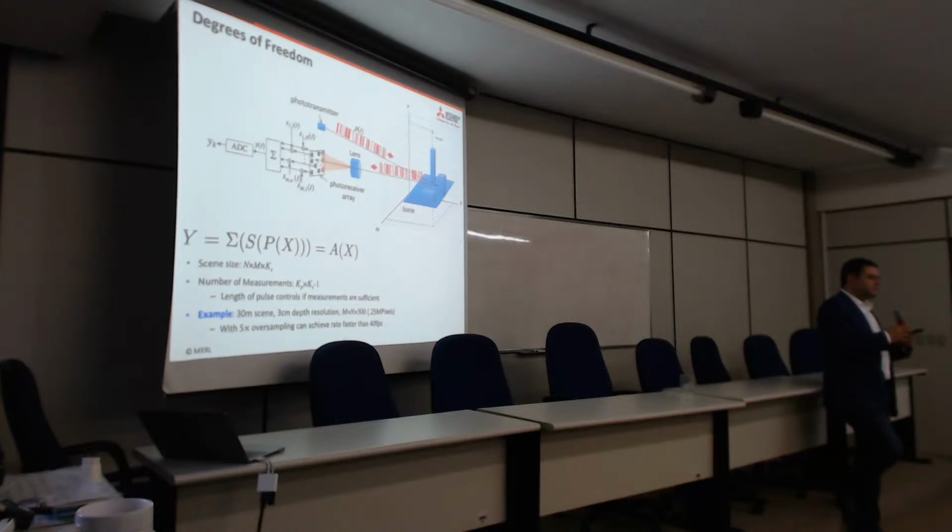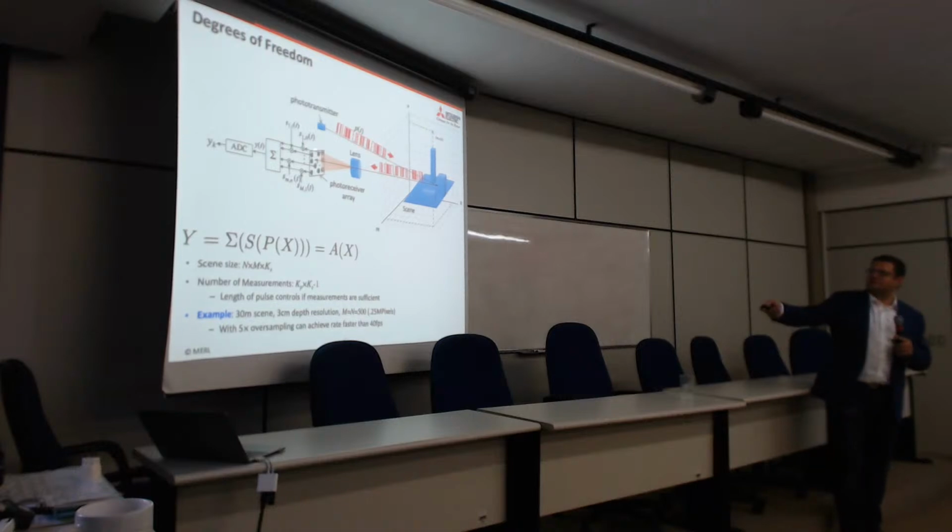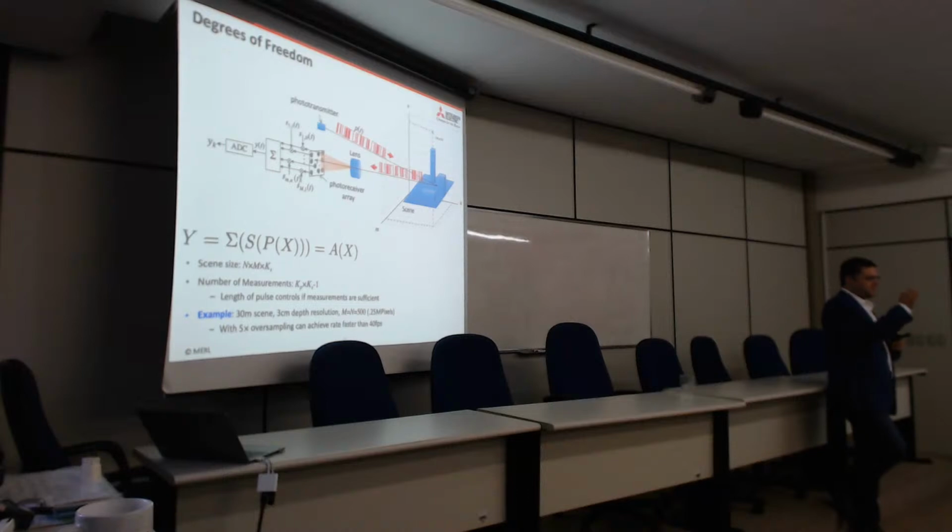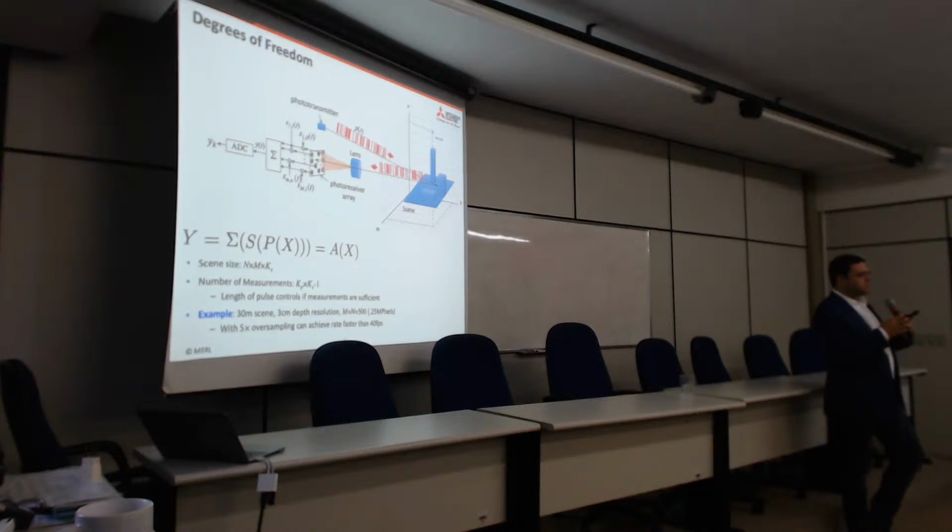The problem is that if you take all that and you buy separate components, for example, a photodiode that satisfies the speed that you have, it will be a big photodiode for one thing, and it will be $1 per photodiode. Once you do a 64 by 64 array, it starts becoming very expensive. Multiplier, same thing. But the cost is not really the photodiode, the cost is all the packaging and the shipping and all that. And that's why it's much more cost effective to build one chip that does everything together. It's just we don't have that expertise.